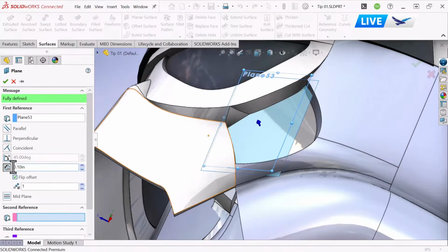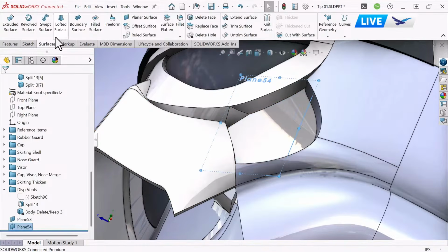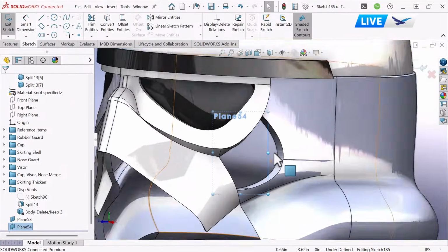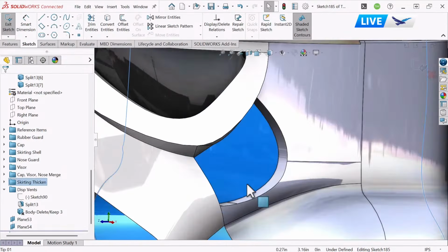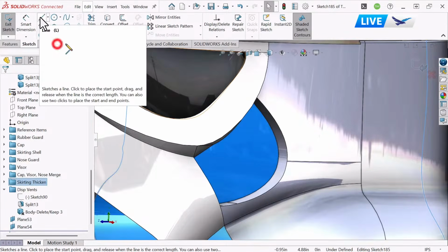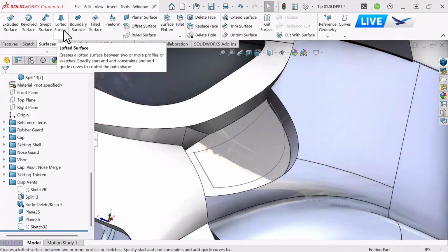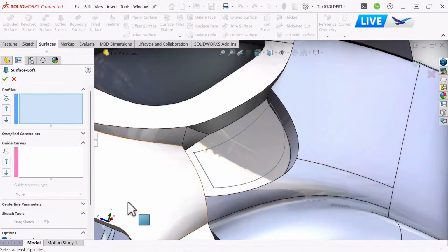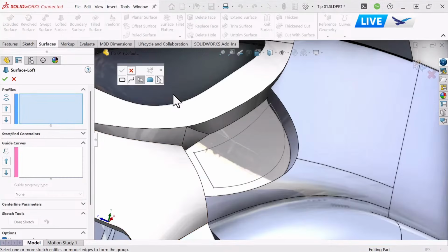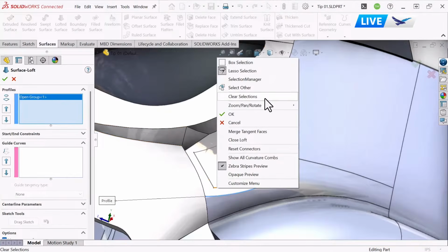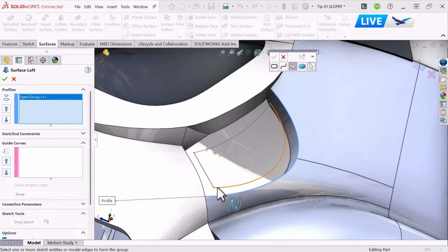Yeah, and I think it's really important for anything that's this organic. There are so many different angles you have to attack things from. With something like this, we're using the 3 vertices. Not only does it give us a general orientation, but it's angled with the model. This is a weird side of the head. It's probably angling in a couple of different ways relative to the orthogonal planes, so it gives us something that moves along the shape we currently have. You nailed it there. There's no place to have a sketch and no plane in the right location. Referencing those 3 points creates a plane relative to where we need to loft, and then creating an offset of that plane is going to maintain that placement.